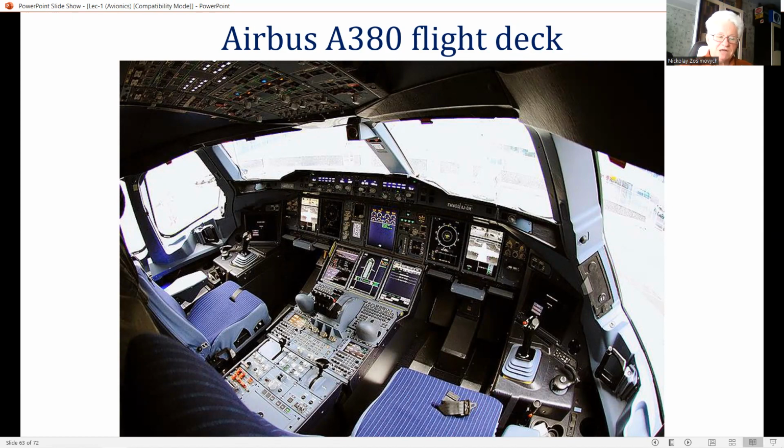The FBW flight control systems eliminate the bulky control column between the pilot and instruments of earlier generation aircraft. This ensures an unobstructed view of the displays. There are also three multi-purpose control and display units, which, in addition to accessing the flight management system, are also used to give systems maintenance data in the air and on the ground.